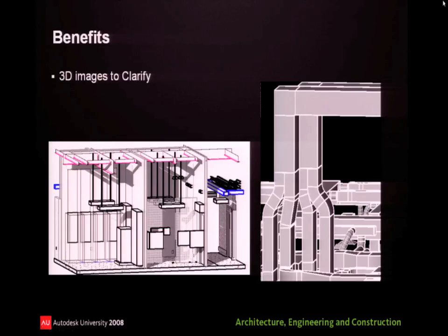But this here was a situation where we had to bring the duct from a rooftop unit, we had to drop through the floor an existing concrete structure, but we couldn't cut the joists. Like, we weren't going to spend the money on bracing the hole in the floor. So we had to straddle the concrete joist. And to show that to a contractor so he could understand what we're trying to do, we put this right on the deliverable, this drawing, to show we got kind of like a pair of pants fitting here as we spread the ductwork to get around those joists. Nice little thing you can do now, different ways of delivering your project.